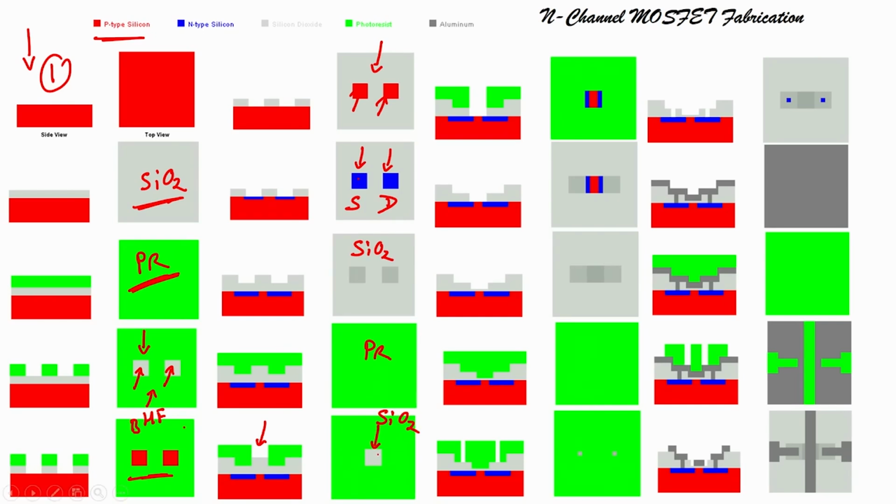When we etch silicon dioxide, you will see this particular region where you can see source and drain, the N type diffusion layers, and in the center there is a p type channel. So, this is what you see when you etch the SiO2. SiO2 was here, correct. So, when you etch SiO2 you reach this particular region.